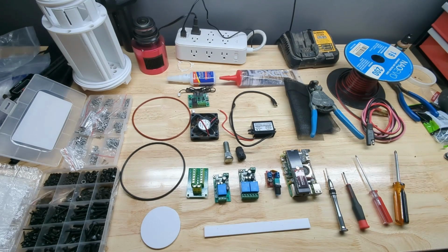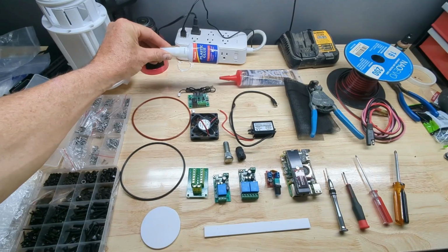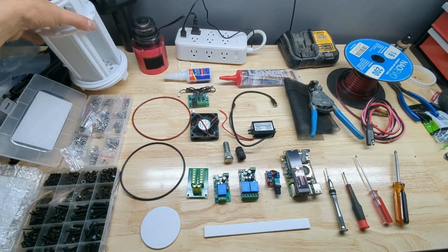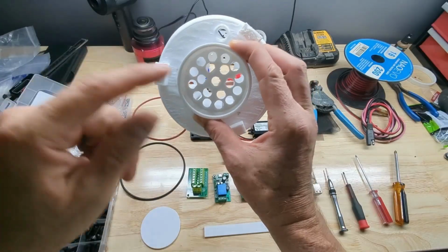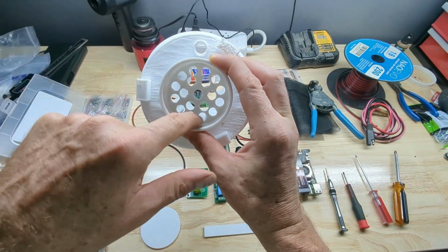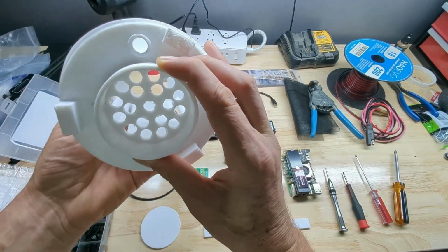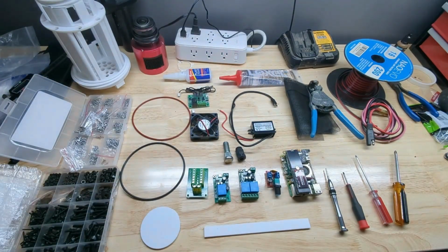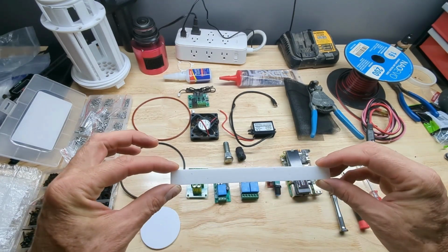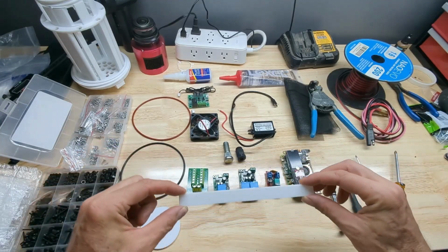So let's get started. The very first component we have here, this is just plastic glue. This will be used to glue the screen to the enclosure. So like on the bottom of this enclosure, this is our fan hole. So the fan sits on the inside. We need to have a screen on here so that we don't pull bugs and other things into it. To make the screen cutting easier, I have these templates here. This basically is the width that you would need for the actual tube enclosure part. You would actually just cut 2 of these.